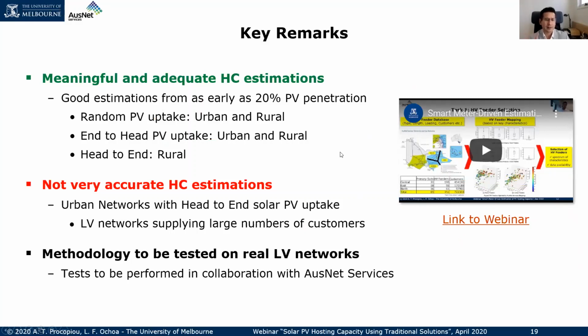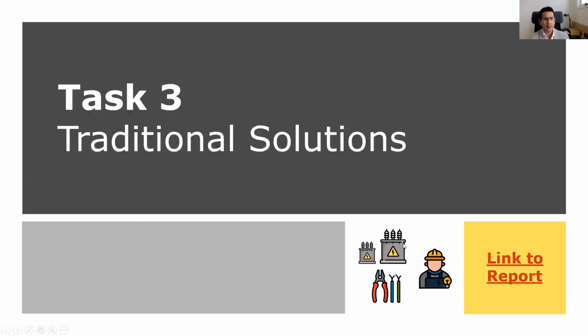But in general, with these analytical techniques, we can actually deliver this particular hosting capacity using smart meter data only. So we were using the simulations to understand the data and to try to find the value from the data, but the technique itself doesn't require any simulations. So you can do this with your existing smart meter data. Of course, it's not perfect, and it doesn't necessarily work with all types of potential cases. There's more detail in the report, but it's a very, very good starting point if we want to use just smart meter data for hosting capacity. Well, that was task 1 and task 2.